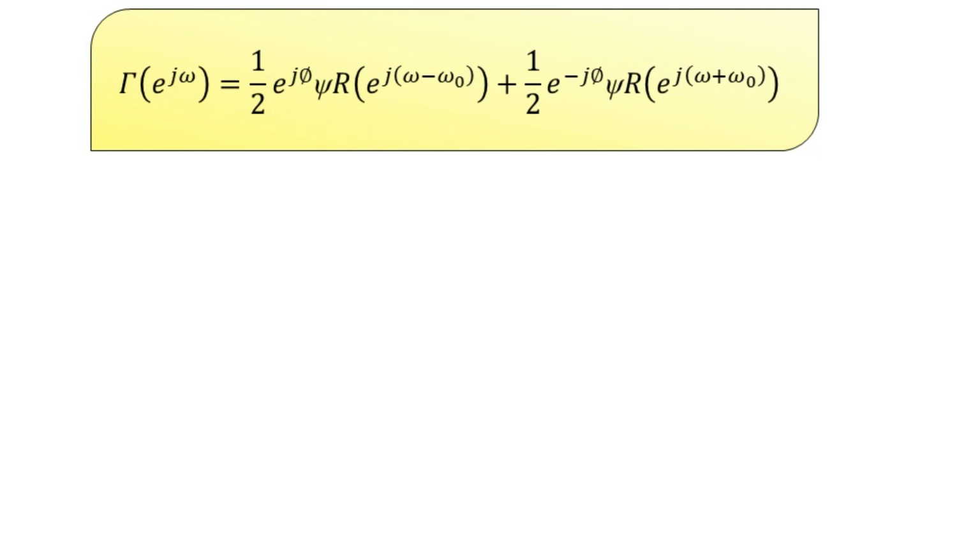Also, there should be a study of the effect of the spectral separation on the DFT of the sum of two sinusoids, and there should be a study of minimization of the leakage using a tapered window. Such complex applications in the signal processing domain, such as the spectral analysis of sinusoidal signals, are of course possible, but with a little bit of increase in computational complexity. So this was the brief introduction to the spectral analysis of sinusoidal signals.